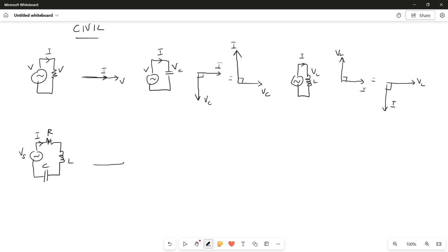Okay, but let's draw the phasor diagram. So this is my reference, and I put my reference at the 3 o'clock position. Yeah, my current's my reference. And just draw this a bit longer. So let's say this is my V resistance, exactly in phase. So following this again for my voltage of the capacitor, if this is my current through the capacitor, then my voltage is downwards.